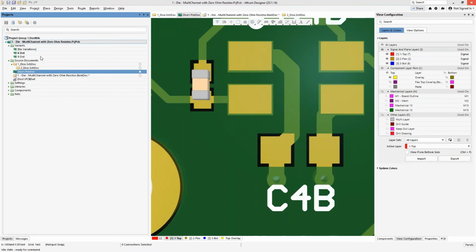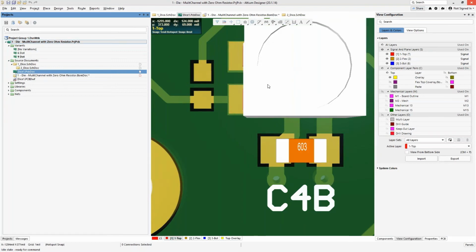So when I go into the 6 dot, this is the alternate part. If I go in the 9 dot, this is the original part and the alternate part goes away. And the capacitor one is really just a matter of whether we fit it or not. So that's how this works. So again, it's about whether we populate the component. It's not about swapping out copper.